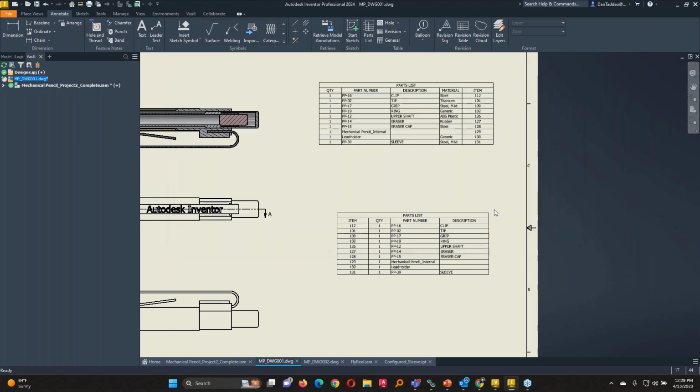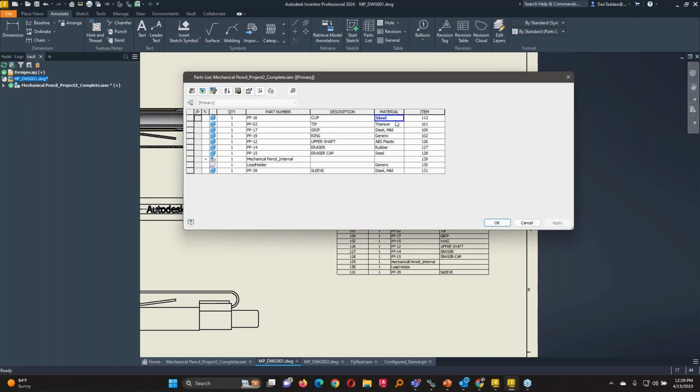If I go ahead and say OK, you'll see it say steel, but if I go to the clip here, you're going to see that it's probably still set to stainless steel because there's not a matching entry for steel. If there is a matching entry, and say I take titanium and I put it up here, it will switch the material for us, but it has to be exactly as it's called out inside of the material library. So the parts list, still showing me that it's overwritten here, does give us the ability, and there are some reasons why we might want to do an override.